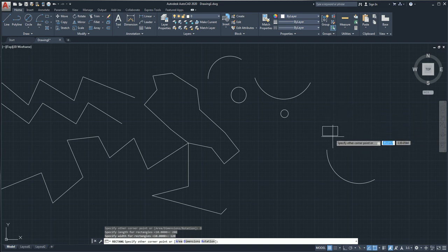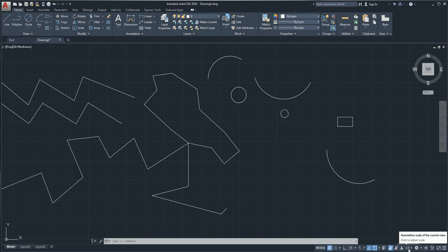So it will ask you which quadrant you want to put your rectangle in. So let's assume we'll pick it here, okay. So I forgot to tell you something very interesting at the beginning. Actually, the scale in this template is 1:1, as I told you, from scratch. When we click on the template, the CAD ISO template, the default scale type of any drawing you are drawing in this template will be 1:1 scale, okay.